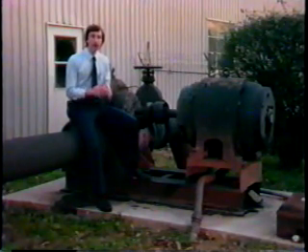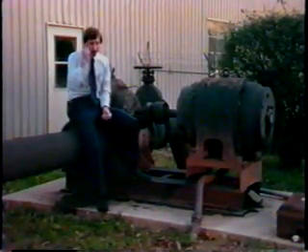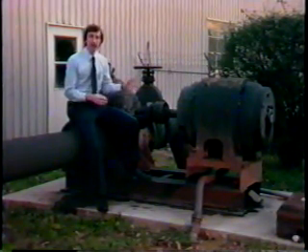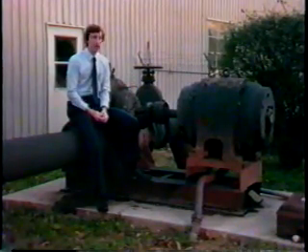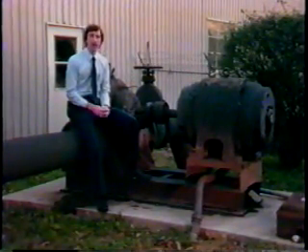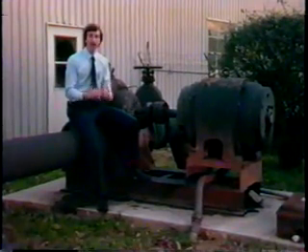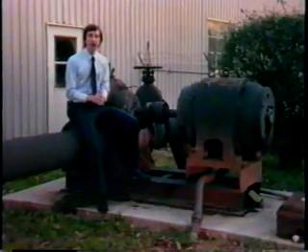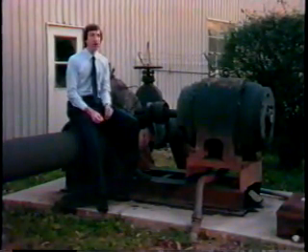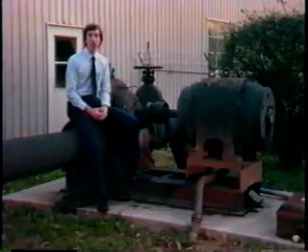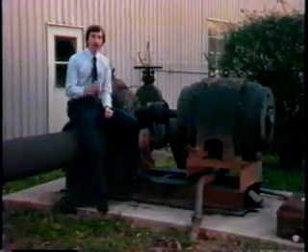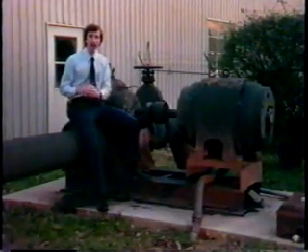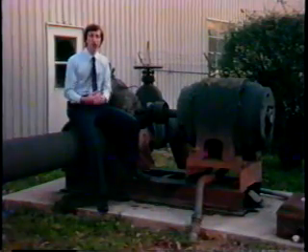Now, if you did not know that this happens, you might think that the distribution mains were losing their carrying capacity when really you were overtaxing the pump that was on. What you want to do during a hydrant flow test usually is to imitate what would happen during a real fire. Therefore, you want to turn on the pumps that would be on during a fire. So if the head at the pumps drops a lot during a test, it usually means you don't have enough pumps on. So you usually, during an actual fire, turn on another pump or maybe even two more pumps.